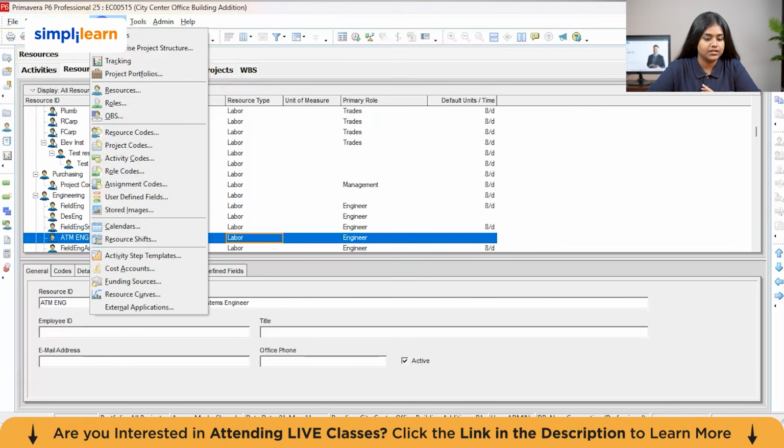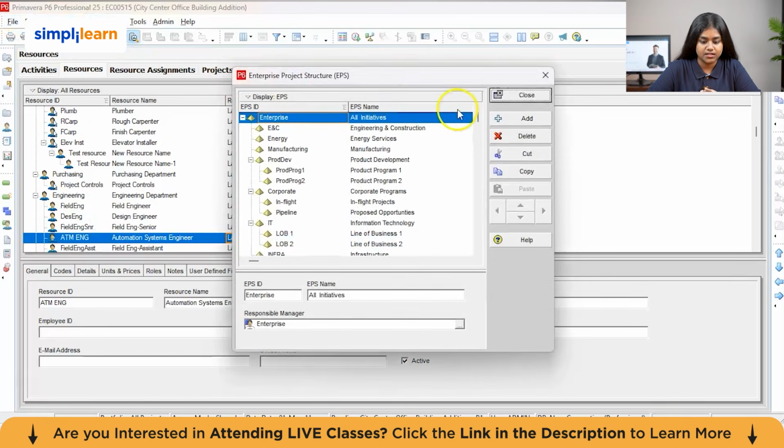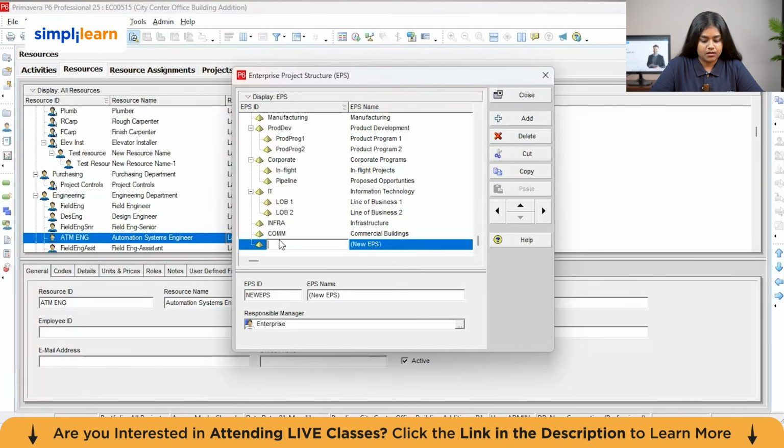So first, we'll create an enterprise project structure, that is EPS. Click on Add. Basically, we are creating EPS because it's a top level hierarchy, and it allows you to organize all of the company's projects into logical groups in the same way that folders can organize files in a computer. For example, a construction company might have an EPS called infrastructure, another called commercial buildings, and a government project. All of these individual projects sit within these nodes.